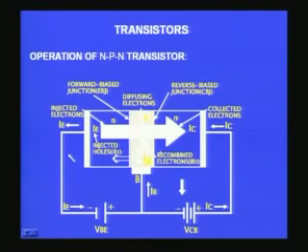The potential barrier in this junction is only for the holes on the left side and the electrons on the right side, whereas what we have now in the base is abundant electrons which have come from the emitter, and therefore they will find that there is actually a valley for them. Therefore they will slide down and go into the collector region.